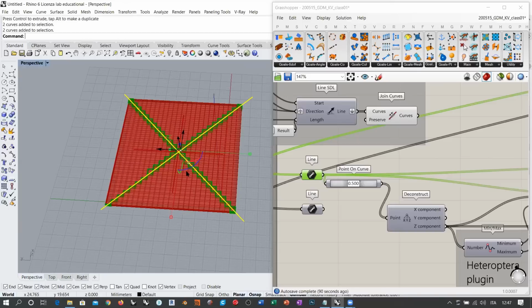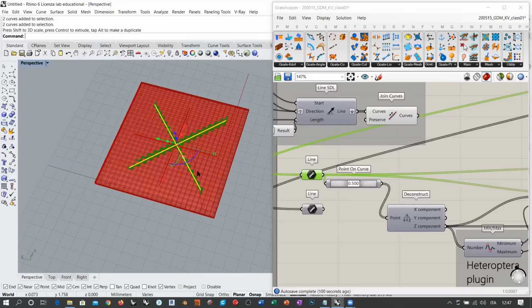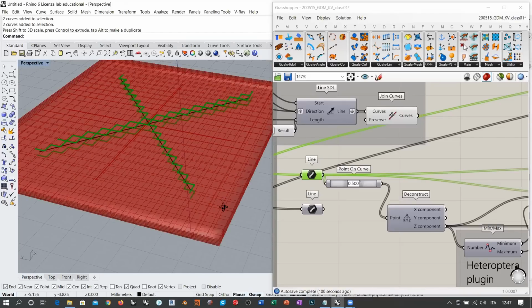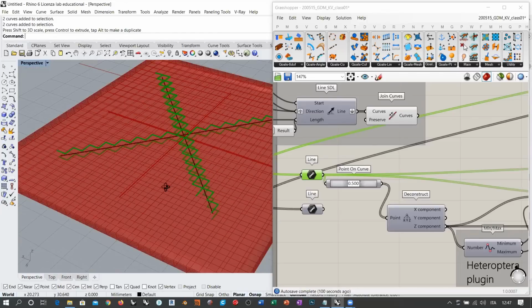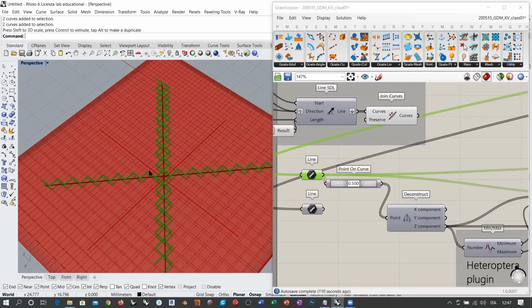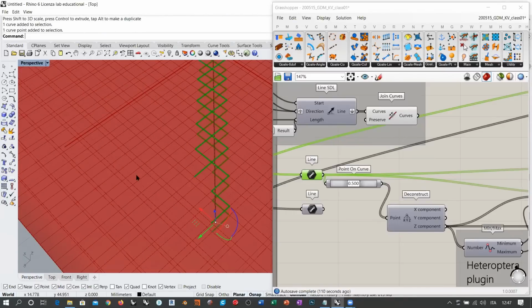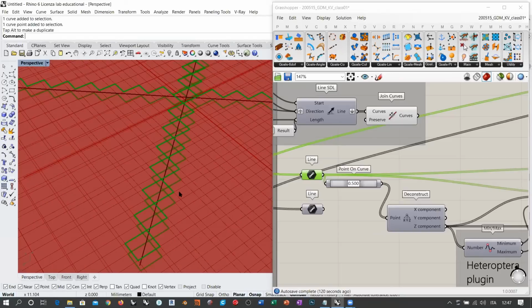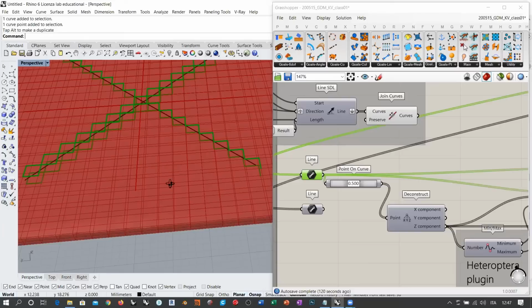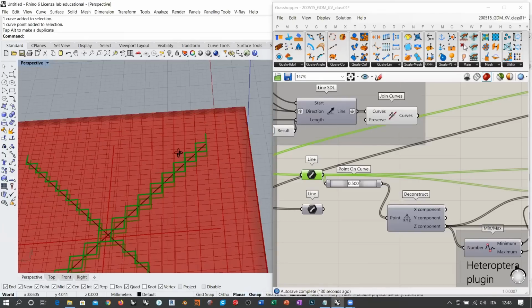But remember that we want to concentrate this at the center of our body. So I'm going to scale this down and eventually double check that the edges are now symmetrical. Let me see. Here we miss some edge at the bottom. All the rest looks just fine. So what I'm going to do, I'm going to take this point here and move it a little more precisely to here, the diagonal. So you see that if you work by hand, you must take into account that there can be some asymmetry occurring, and you must always double check that things are working properly.